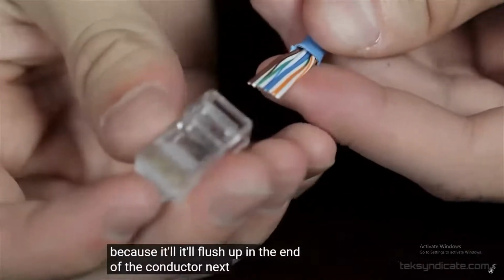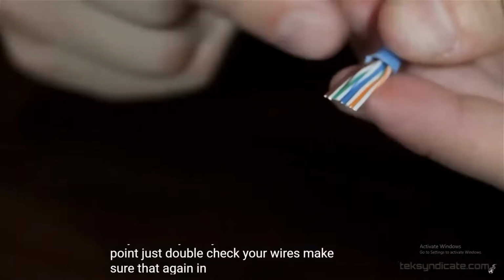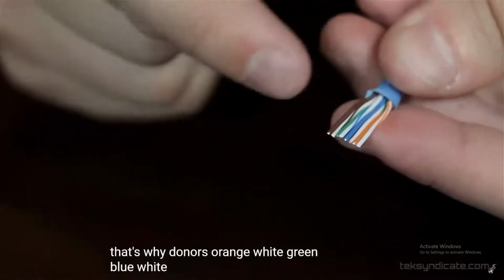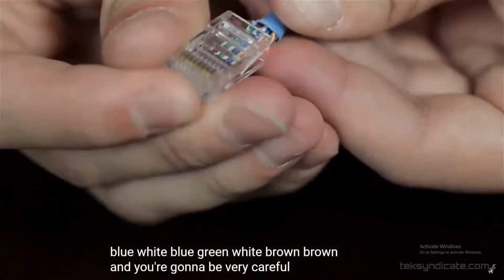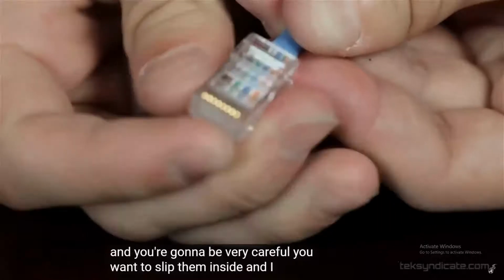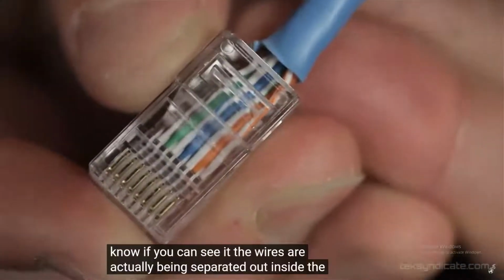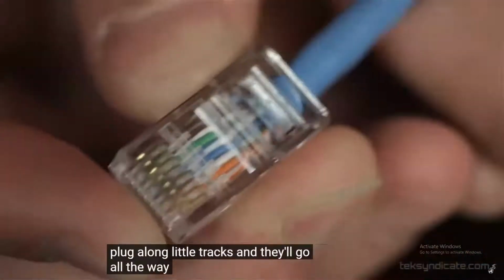Next, we're going to very carefully, and at this point, just double check your wires, make sure that they're again in the correct order. That's white, orange, orange, white, green, blue, green, white, brown, brown. And you're going to be very careful. You want to set them inside, and I don't know if you can see it. The wires are actually being separated out inside the plug along little tracks, and they'll go all the way.